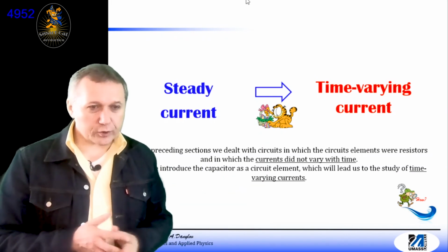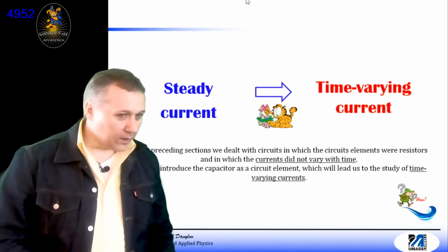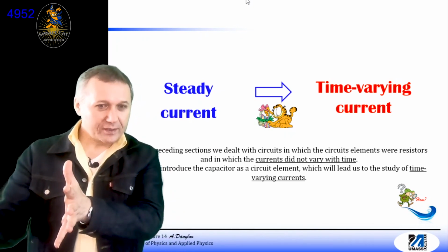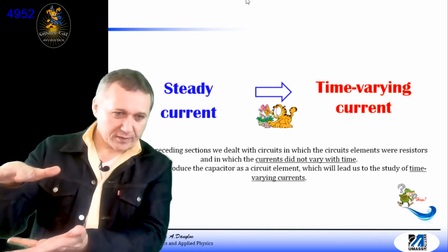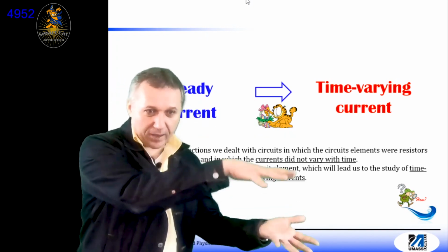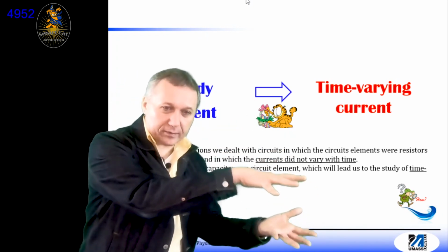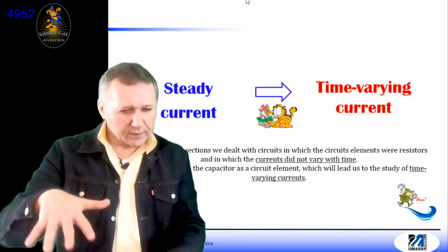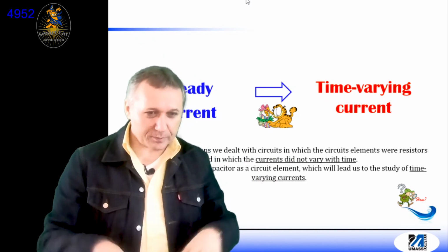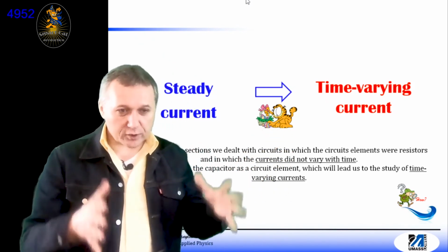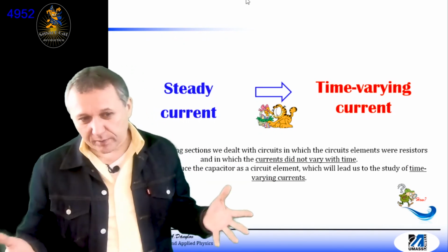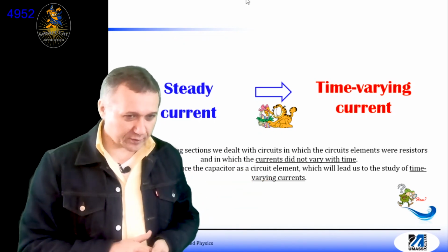So how are we going to change the current? There will be a capacitor, first an empty capacitor, and of course we can charge that capacitor. In order to charge it, we need a source of charges, a battery. If we connect a battery directly to a capacitor, the process can be too fast, and we can damage our capacitor. So it's better to slow things down. It's better to connect them through a resistor, so the current will be reasonable and we will not cook this circuit.